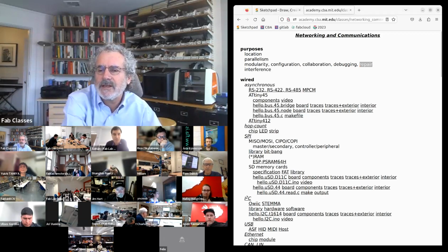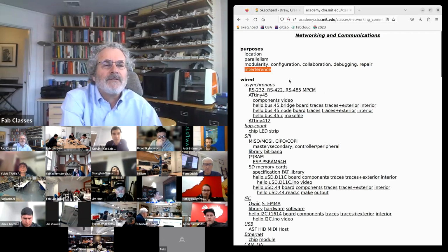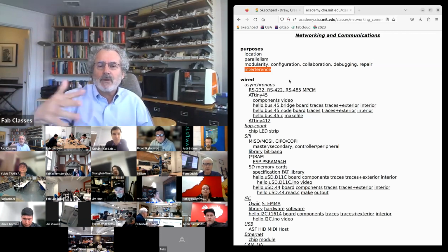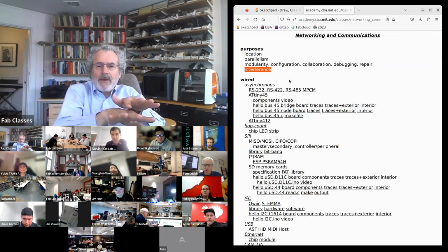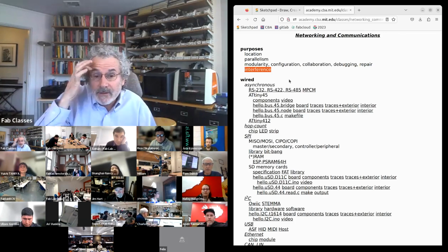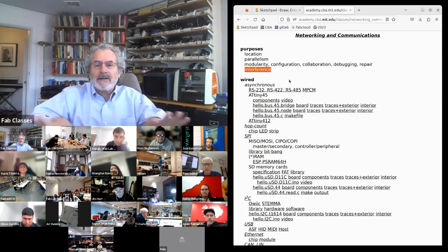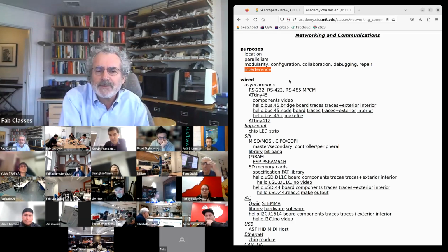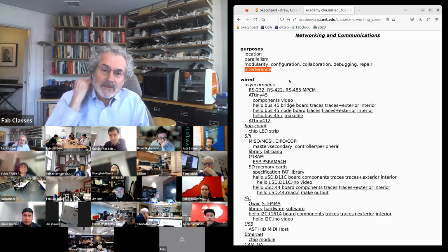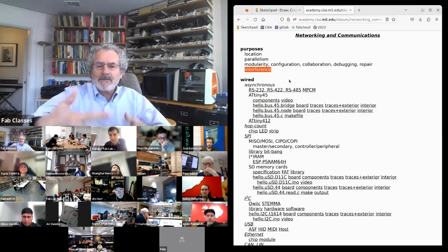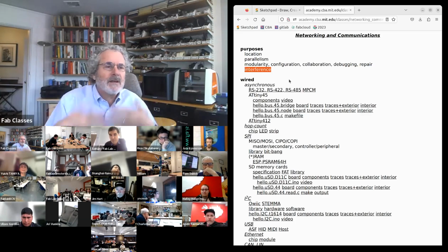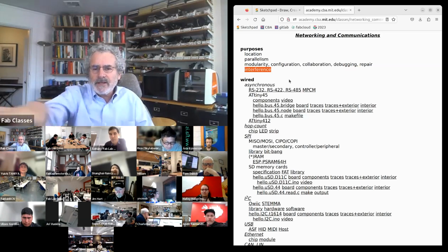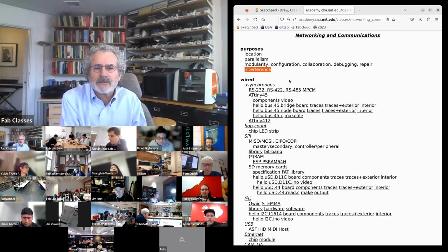And then a final benefit you get from that is one part of the system might have high voltage, one might have high current, one might be measuring very low level signals. And so by breaking the system into modules like this, you can prevent interference. So there's strong reasons to make a network, even if it's only in one box. Or another example is in the machine building we saw, we're moving from central controllers to machines that are networks for all of these benefits.